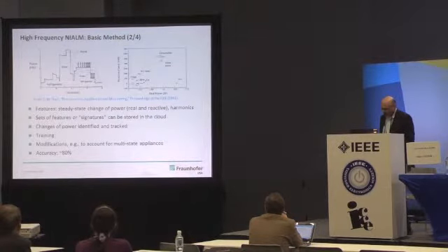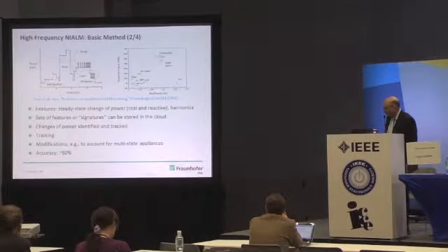Once the clusters are identified, positive and negative clusters of similar magnitude are paired or matched, and in the fourth step, known as anomaly resolution, unmatched clusters and events are paired or associated with existing or new clusters according to a maximum likelihood algorithm. In the fifth and final step, pairs of clusters are associated with known power consumption, so that each individual end-use load can be tracked continuously in time.